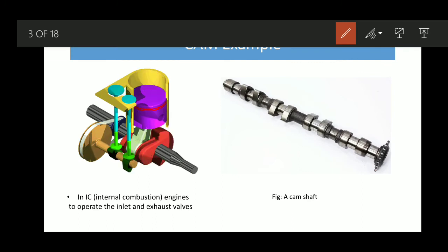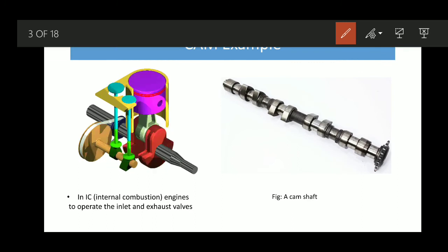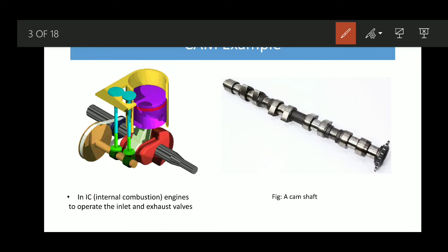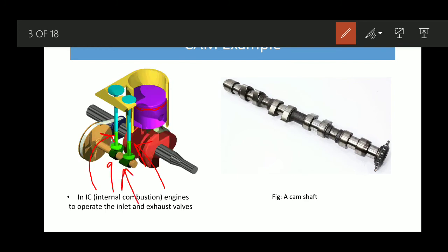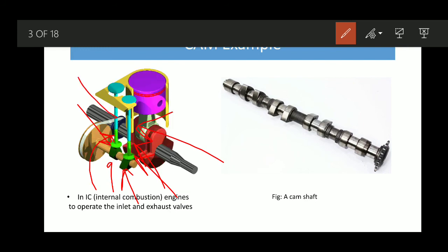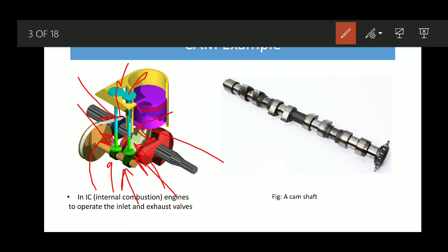So in this particular case our requirement is something like this. Suppose we consider the two valves shown here. This gray part, these are the two cams which are responsible to give the motion to the two valves of this particular engine. The two green parts are the followers, which are in constant contact with the cam, and the motion of each follower is given to the blue extension part, which operates the valves. As you can very easily see here.